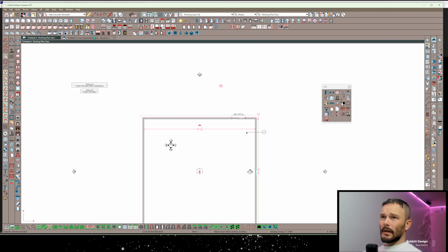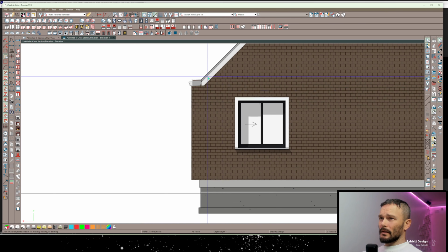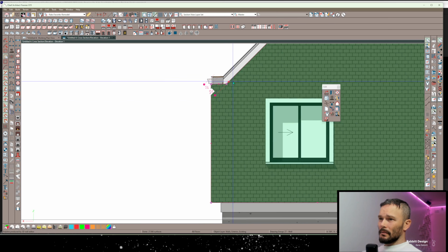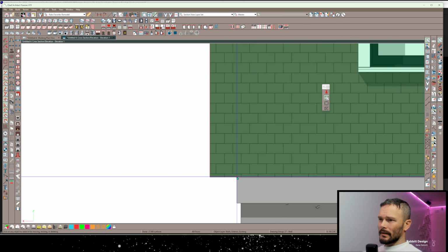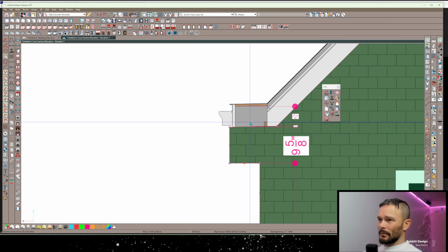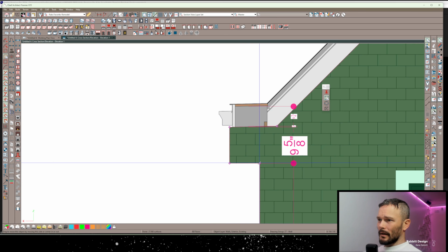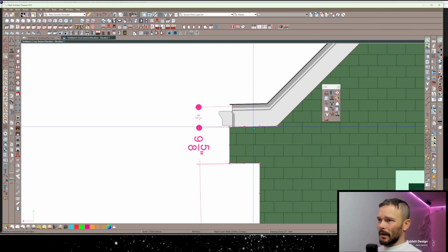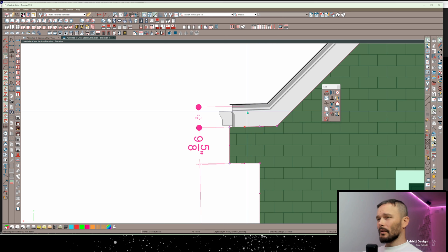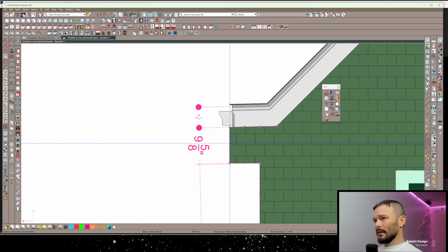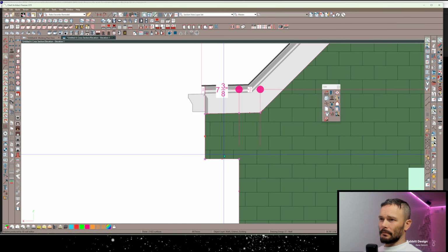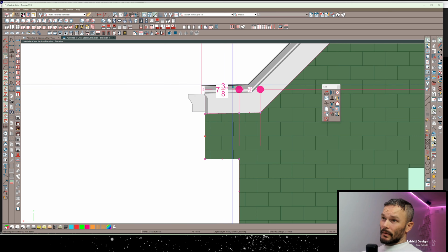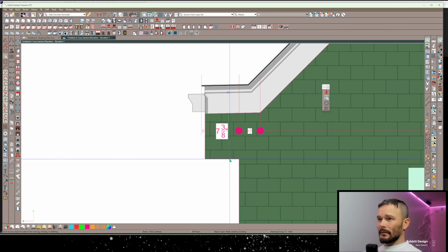So now we can get to our elevation. Let's take a look at what we've got so far. You can see here, we've got the makings of what we're looking for. So I'm going to go ahead and make a break here right along this line of my siding wall. And I can drag this up. Now, before I get too far into this, I want to make another break, and I'm going to infer from this first break, which is right along that siding wall, and look what happened. All of a sudden, it revealed our soffit, right? Our gable trim.